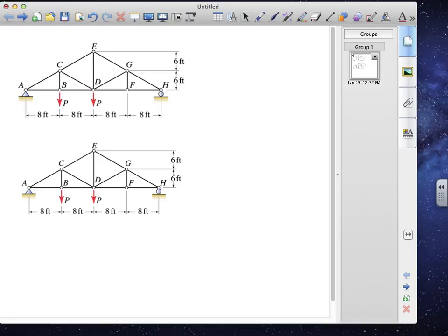First, the truss is statically determinate, so a good way to start is to find the reactions at A and H. We'll get to that shortly, but for now, let's assume we know how to do that and we can find those reactions. Then how should we proceed? The issue with member DE is that it's as far removed from the support reactions as possible. We're going to take a look at 2 solution strategies, of which there are actually many.